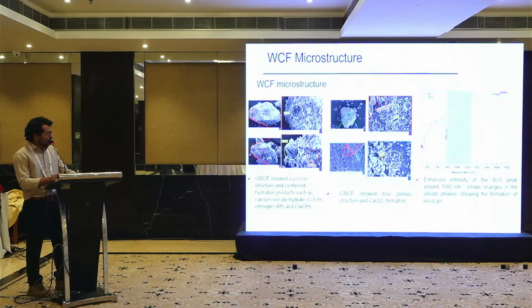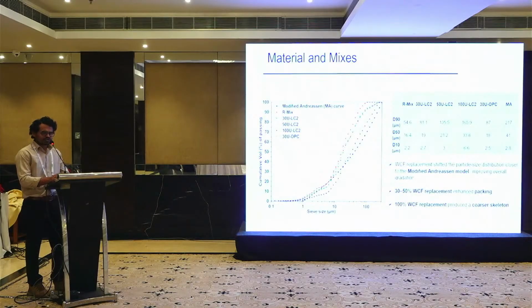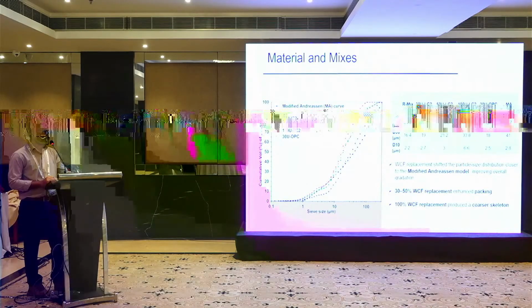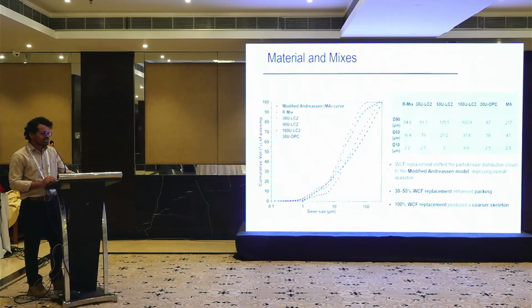The waste concrete fines are a finer material, but I am checking how it affects the optimum particle packing. The Andreasen model is used here. As the replacement goes on, the D90, D50 and D10 sizes shift towards the optimal packing curve, whereas at 100% replacement it shows a coarser skeleton.